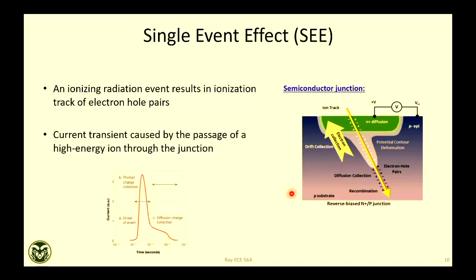So in a small time, if you look here, the time is in a picosecond time scale. You see a transient current pulse, created because of this PN junction effect and carrier generation along this junction. This current pulse can be enough to flip your SRAM cell, for example, or to flip your DRAM bit. That's how you see single event effects or single event upsets in a memory, because of this transient phenomenon, which is carrier creation along a PN junction.